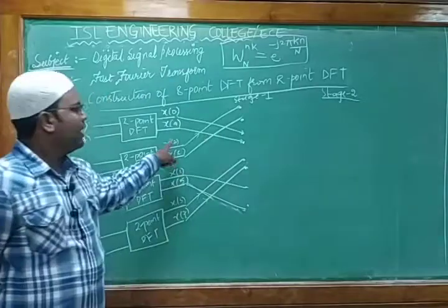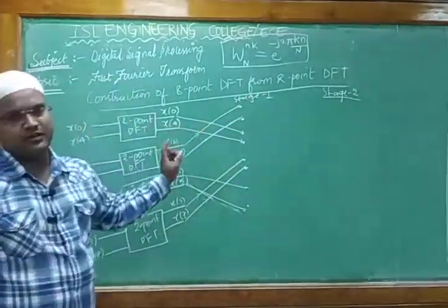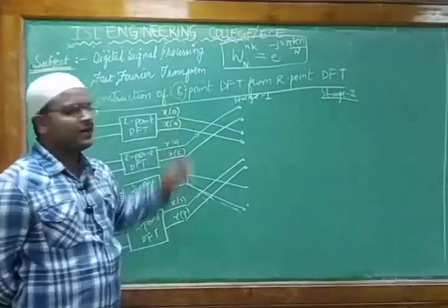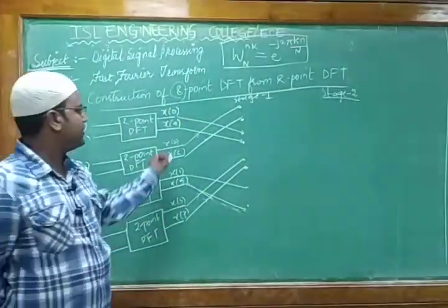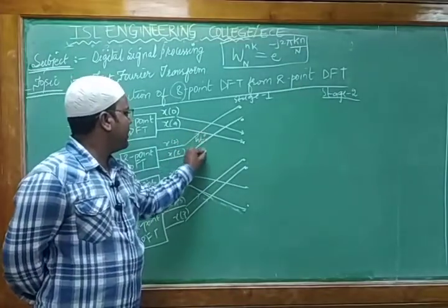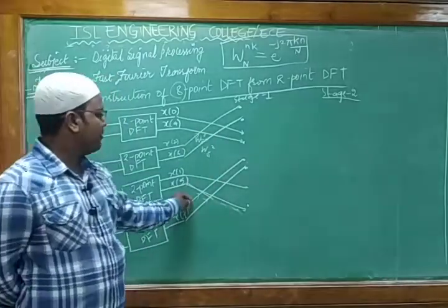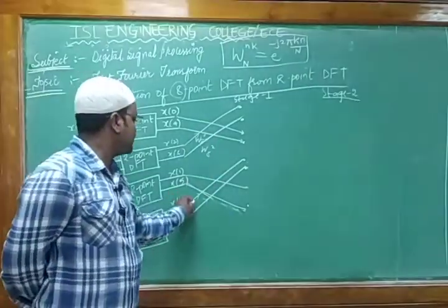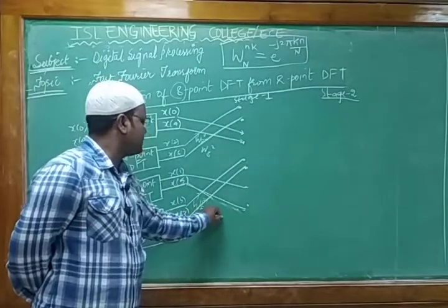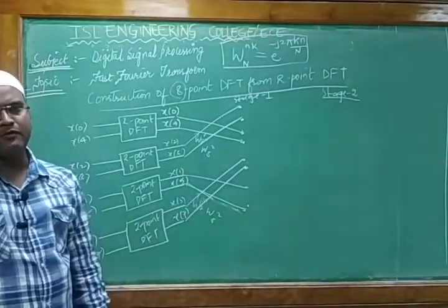Since it is stage 2, when we are going from 1 to 2, we will write the weighting sequence. So since it's how many point sample? It's 8 point sample. So that's the reason we'll mention W8 of 0 here, W8 of 2. Same way we can go for the next part. Here also we'll take the next two. We can write it as W8 of 0 and W8 of 2. Whereas the first indicates the first sample value and the second indicates the second sample value sequence.